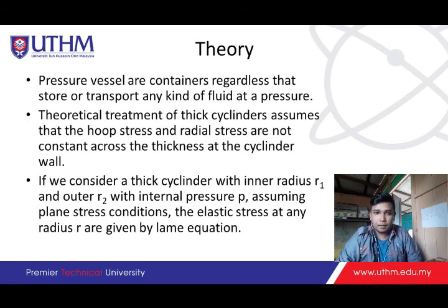For the theory, pressure vessels are containers that store or transport any kind of fluid at a pressure. The theoretical treatment of the thick cylinder assumes that the hoop stress and the radial stress are not constant across the thickness of the cylinder wall. We consider a thick cylinder with inner radius R1 and outer radius R2 with internal pressure P. Assume plane stress condition. The elastic stress at any radius R is given by the Lamé equation.